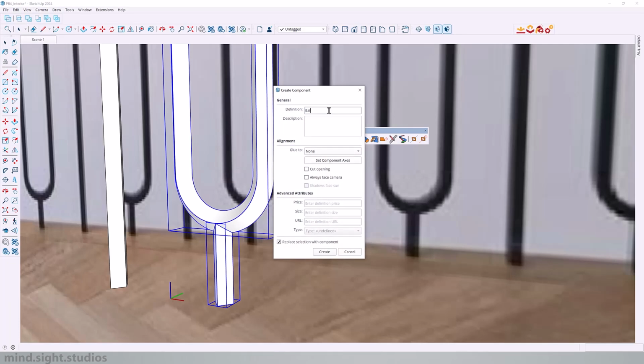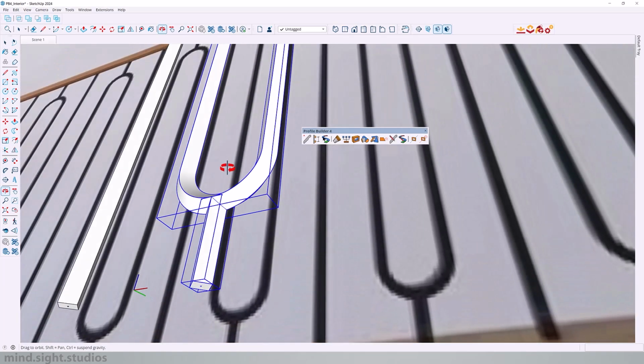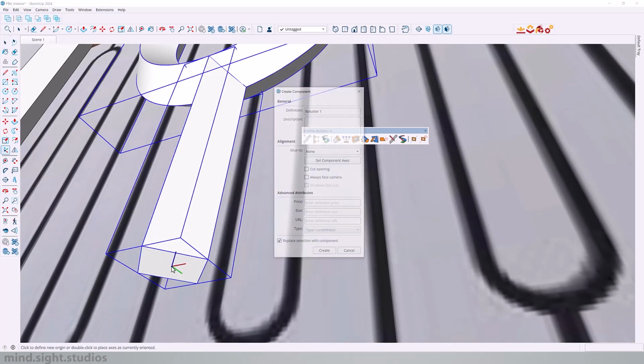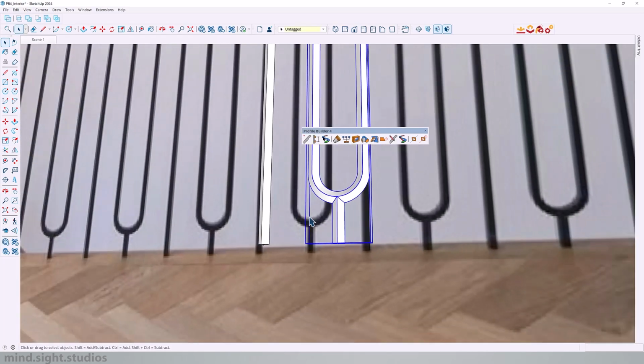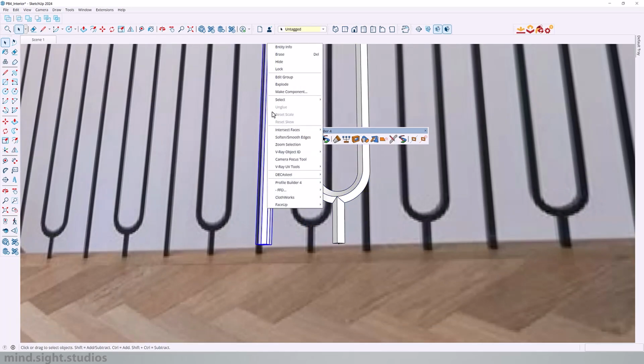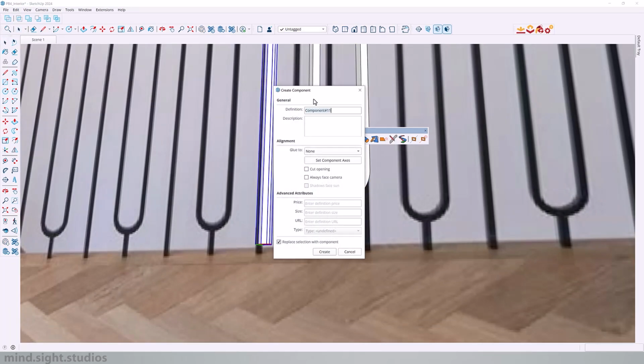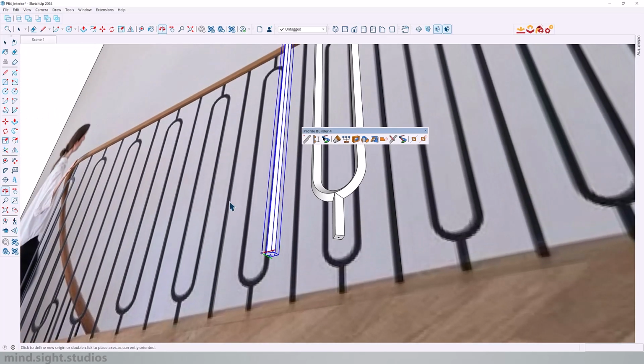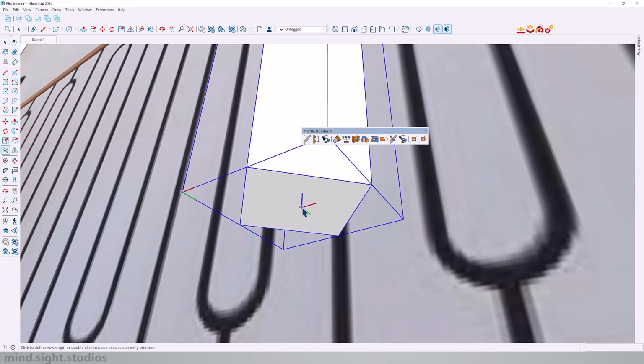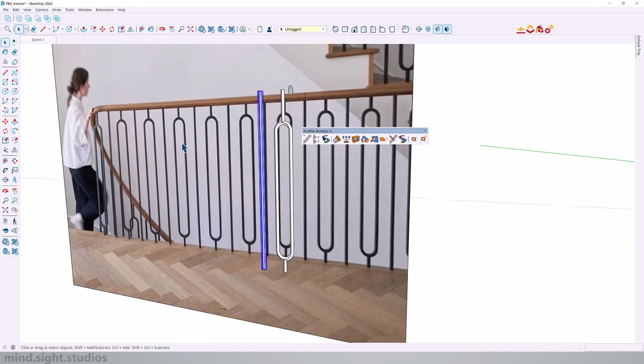components. You want to make sure they are named properly and set the axis to the bottom center of your component. In order to do this, it's always a good idea to set the center point at the bottom center of your component and use that as a reference to set your axis. So take this as a rule of thumb for every component you use in Profile Builder, as this is one of those steps you don't want to get wrong.